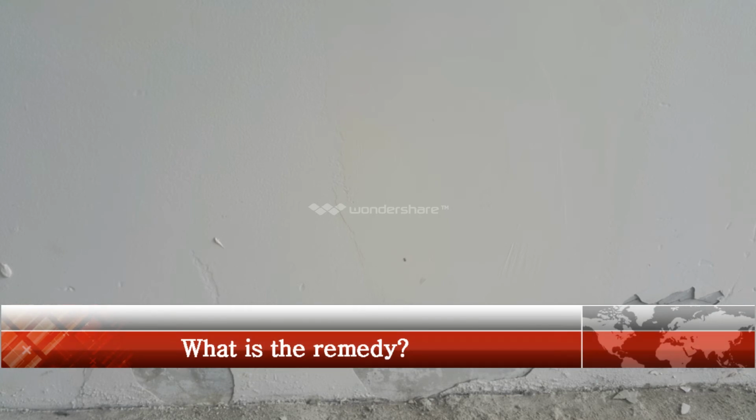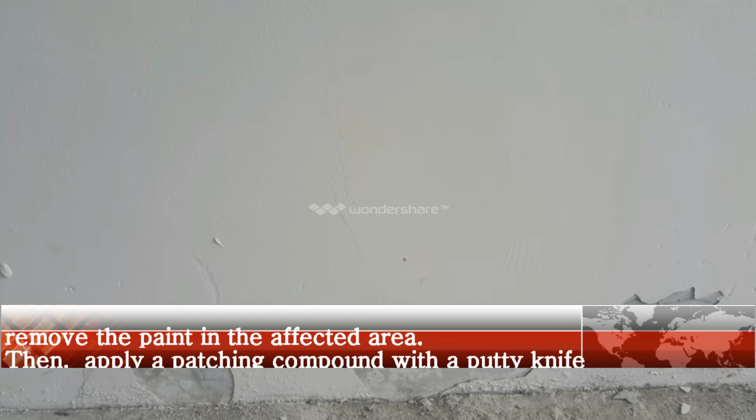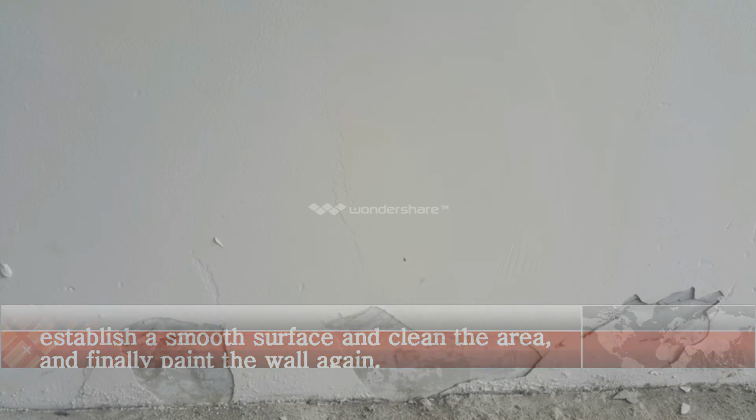What's the remedy? Firstly, remove the paint in the affected area, then apply a patching compound with a putty knife. After that, establish a smooth surface and clean the area, and finally paint the wall again.